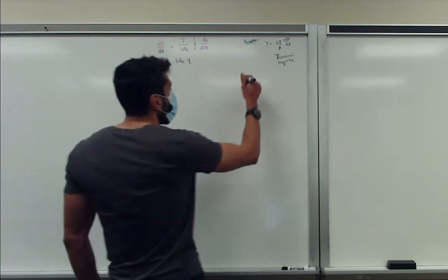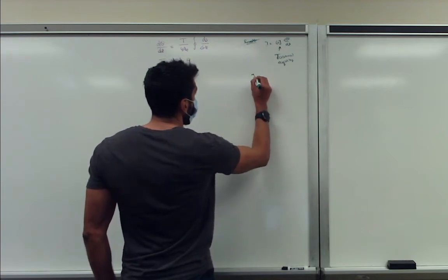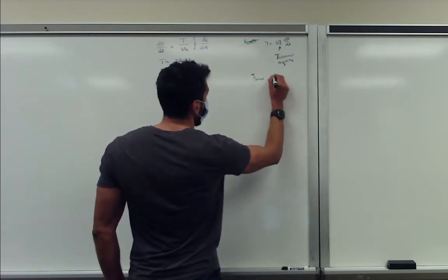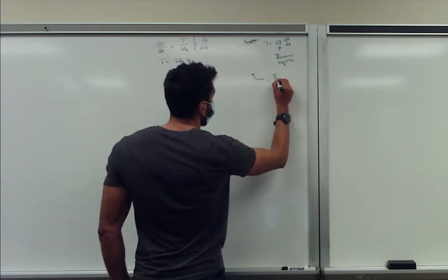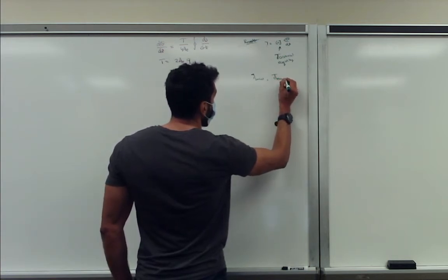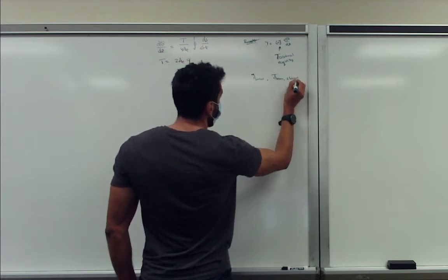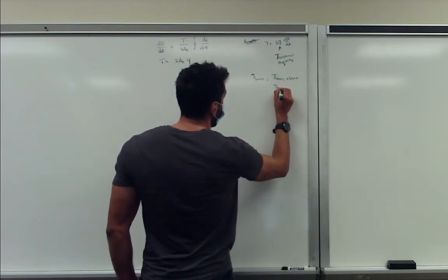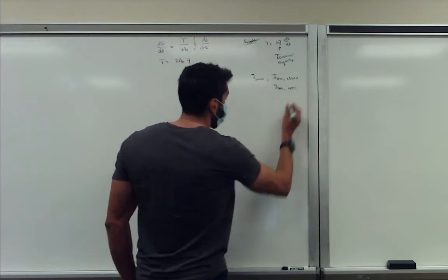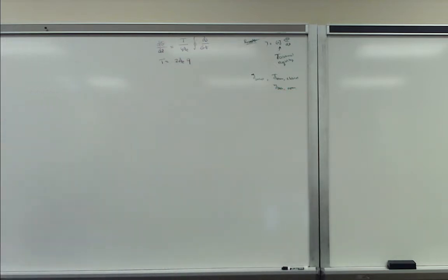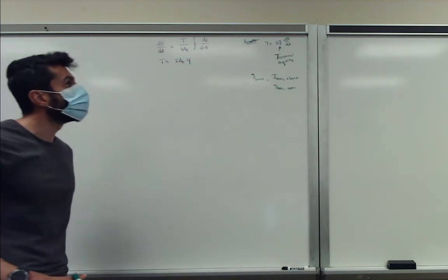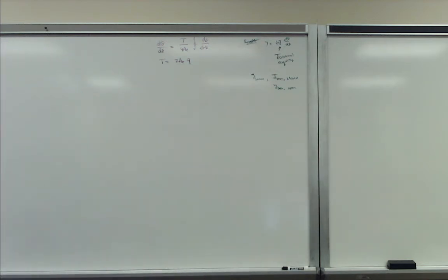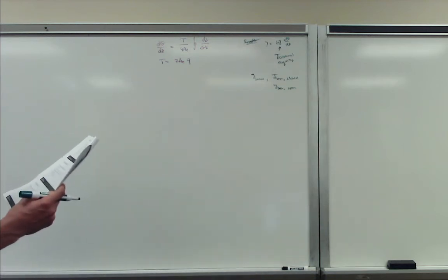And if we want this J for solids, we already know, and we also want to have a J for say thin-wall closed sections, and eventually we also want to have a J for thin-walled open sections. Because the torsion rigidity will give us a pretty good idea, similar to our moment of inertia, of how effective a certain cross-section will be in handling, in this case, torsion. So we derive the same thing, but then for a thin-walled section.